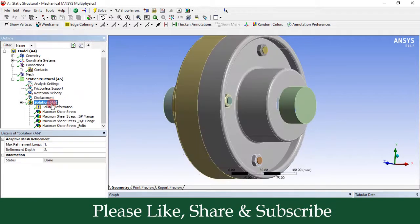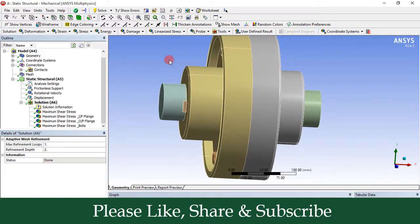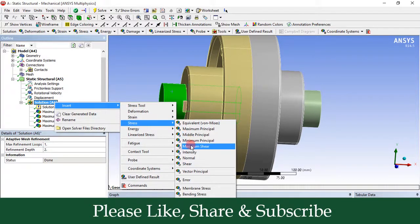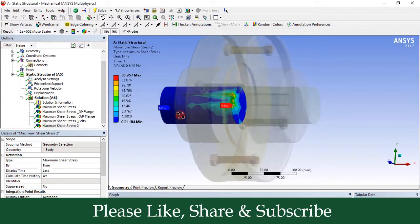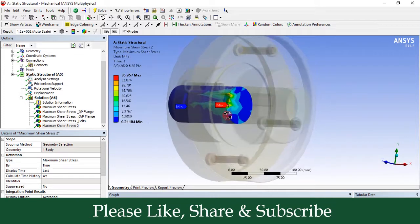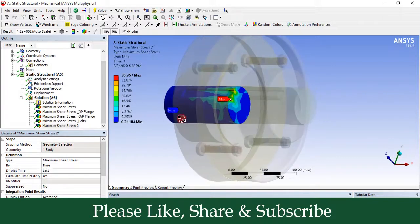Now let us check similarly the maximum shear stress for input shaft and output shaft. So again, in order to select the input shaft, we have to go to this body button, select this input shaft, left click on solution, right click on solution, go to the insert, go to the stress, select maximum shear stress, and then again right click on it, select evaluate all results. So you can see here this is the stress variation in the input shaft. So you can see here this is the point of maximum shear stress and this is the point of minimum shear stress in the shaft.